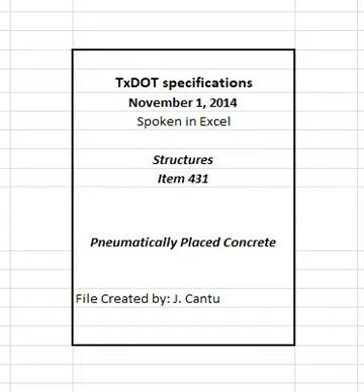3.4 Pneumatic placement of concrete. Pneumatically applied concrete can be either dry mix or wet mix. The dry mix process consists of dry mixed fine aggregate and hydraulic cement to which water is added immediately before its pneumatic expulsion from a nozzle. The wet mix process consists of mechanically pre-mixed concrete pneumatically applied through a nozzle.